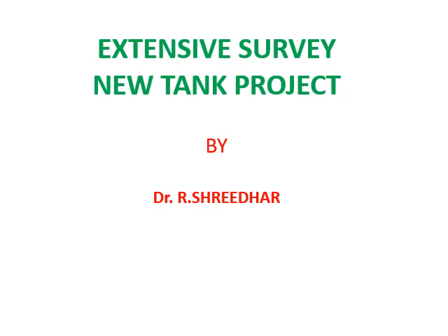So you should know that the catchment area and the reservoir area are totally two different quantities. The catchment area should be got from the topo sheet, and the reservoir area can always be calculated from the capacity contours that you have generated after doing a total station survey for the reservoir area.